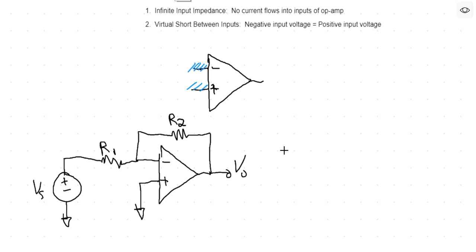So what is an op amp used for? Well, it stands for operational amplifier, and the quick and dirty of it is it'll take an input voltage and amplify that input voltage so that the output is some predetermined multiple of the input. When I say predetermined, the gain of an op amp is by design. And what's cool about the op amp is the gain is controlled by external circuitry.